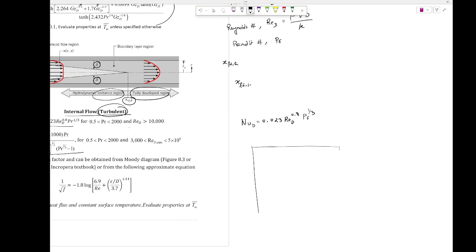The chart should look something like this. You have the friction factor here and the Reynolds number here. I remember it by heart, that many times I've read it or learned it. Then you have this E by D, where D is the diameter and E is the smoothness of the pipe. Different pipes have different smoothness, right?